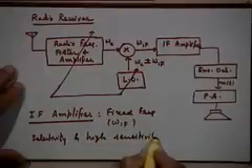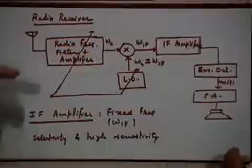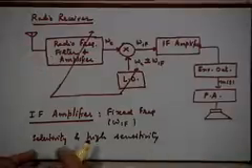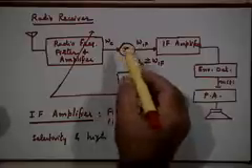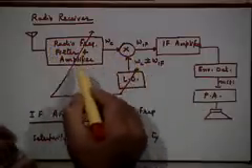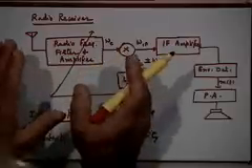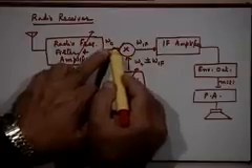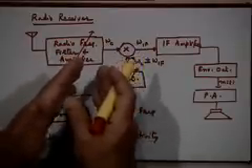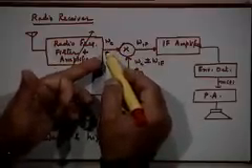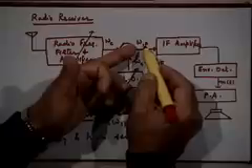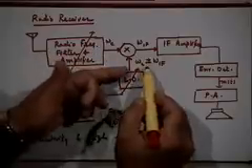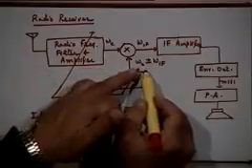These are very easy to build in an amplifier of fixed frequency rather than an amplifier of variable center frequency, right. So you can make it highly selective. Suppose the RF amplifier here does not do its job well, so two signals which are close by will come out here. It will not be just omega c, but a few other frequencies close to omega c will also come out here with some amplitude. So they will also be present here, but their frequencies will be slightly different, because they are not exactly removed from the local oscillator frequency by omega if, right.